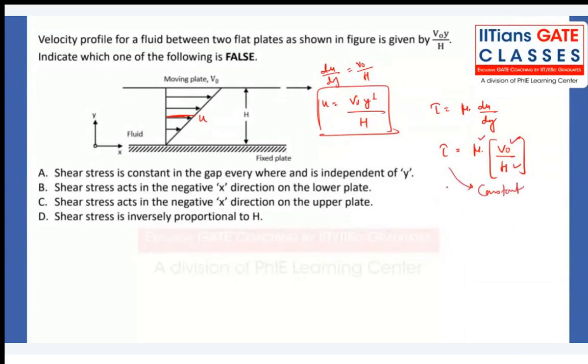The shear stress will be acting in the negative x direction onto the lower plate. Correct or incorrect? Shear stress is inversely proportional to h. That is a correct statement. The shear stress is constant in the gap everywhere and independent of y, as you can see from this equation. That is also correct.